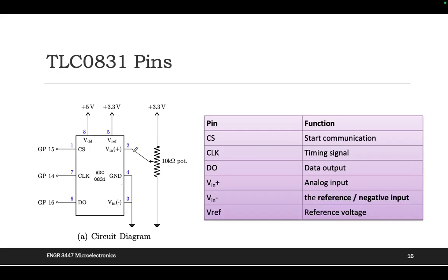Okay, and this is the reference voltage, which means the biggest voltage I can read in this circuit. You can see here, this is 3.3, because for our Pico, we use 3.3, am I right? Okay, but let me ask you a question. Can this voltage be changed? This 3.3? Probably no.